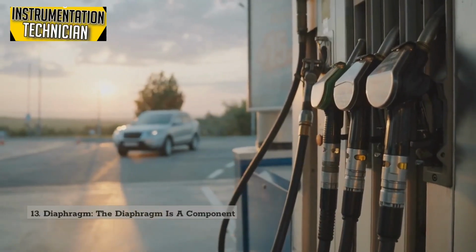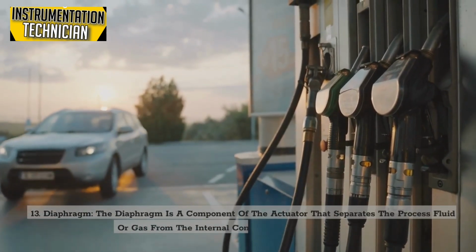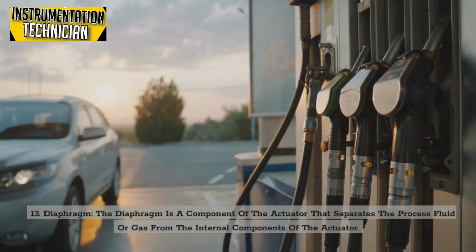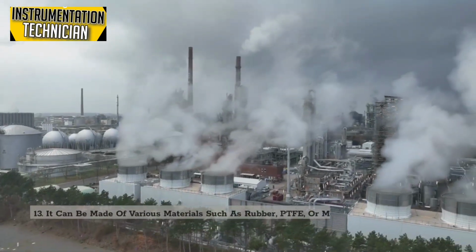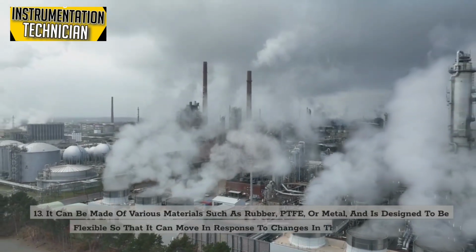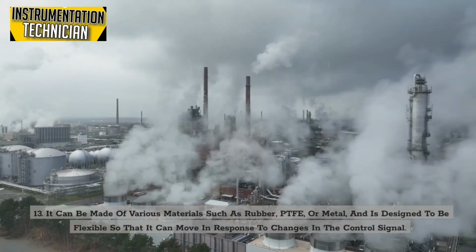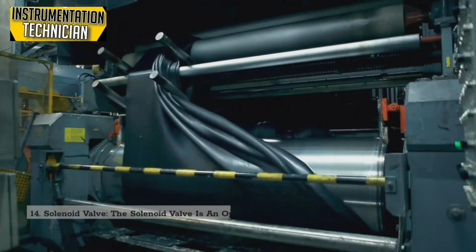13. Diaphragm. The diaphragm is a component of the actuator that separates the process fluid or gas from the internal components of the actuator. It can be made of various materials such as rubber, PTFE, or metal, and is designed to be flexible so that it can move in response to changes in the control signal. 14. Solenoid valve.